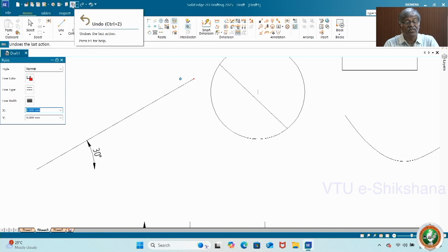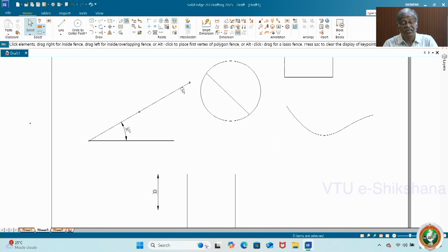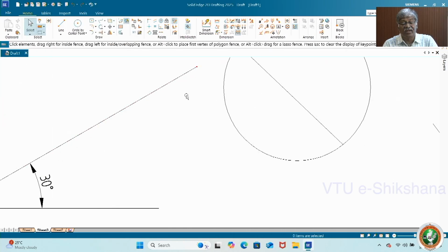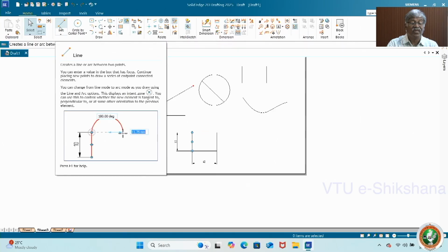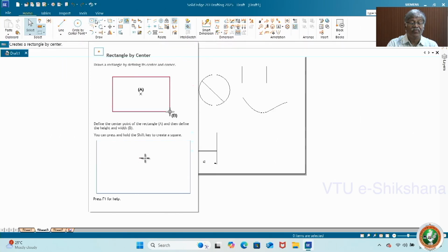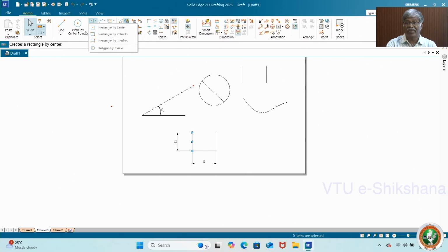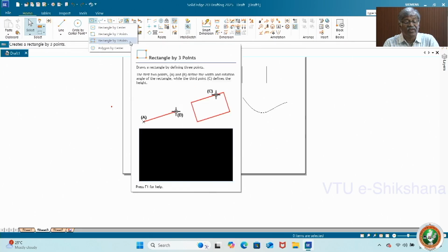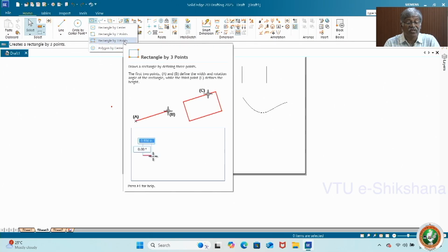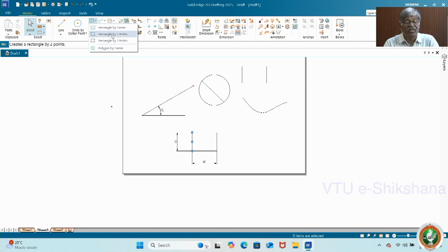You can see this dot, red color. If you need repetition, you can do undo and see. You can see the red color dot available here. So this is point. This is how you create point or mark points in between. So the necessity of these commands and the tools is very important, and also we can create the rectangles using different options.